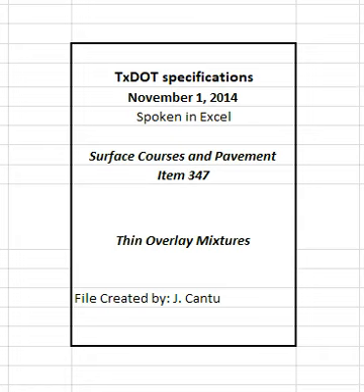4.4.2.1.7 Boil test. Perform the test and retain the tested sample from TEX 530C until completion of the project or as directed. Use this sample for comparison purposes during production. The engineer may waive the requirement for the boil test.